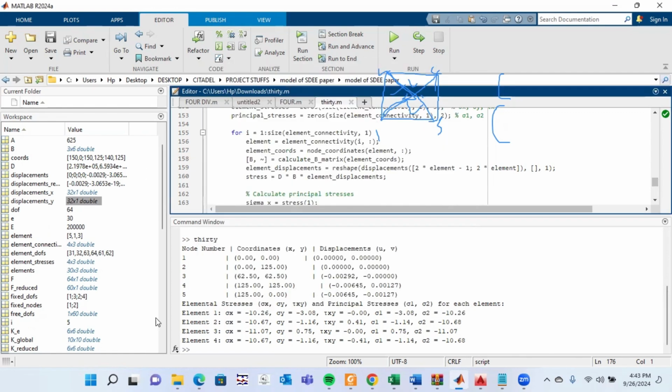And obviously our answers, for those of us that have been using MATLAB, this left side is a little bit self-explanatory, right? From the very onset, you know that you're working with 5 nodes, 2 displacements, 2 degrees of freedom at each node. So that's 2 times 5, that's 10 degrees of freedom, right? So your matrix is going to be 10 by 10, isn't it?